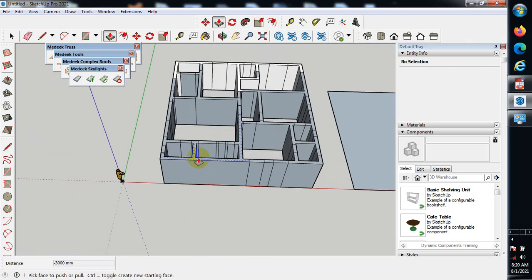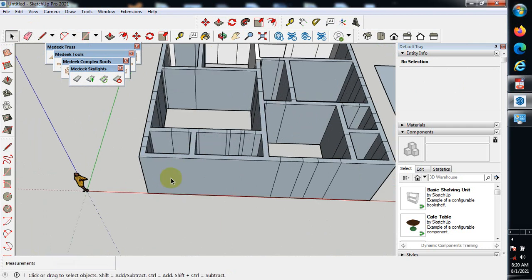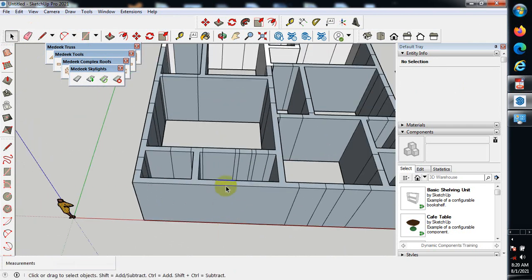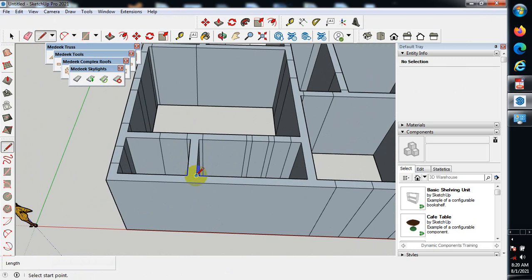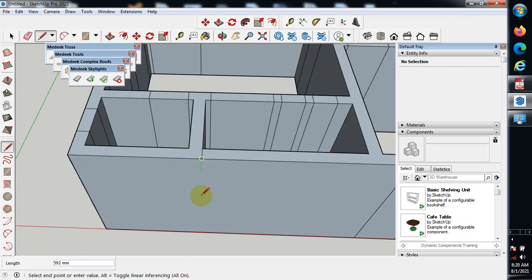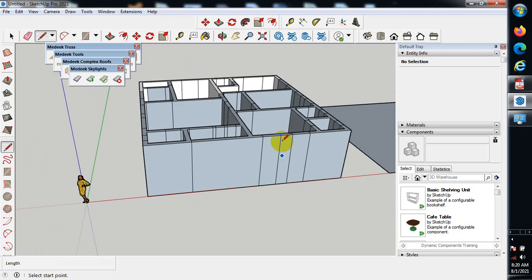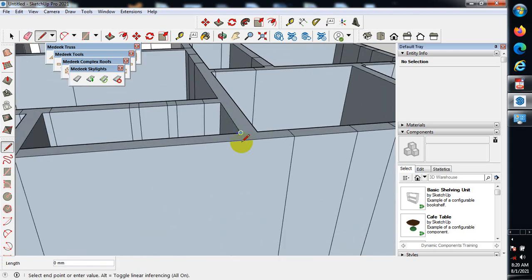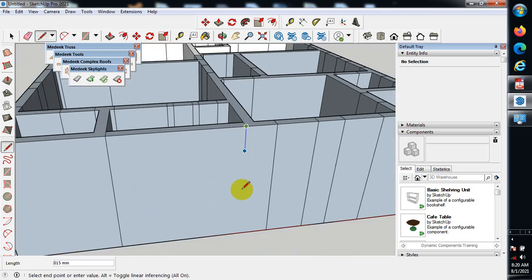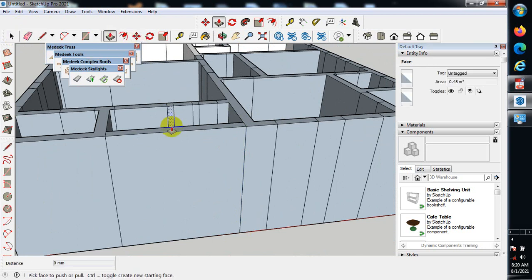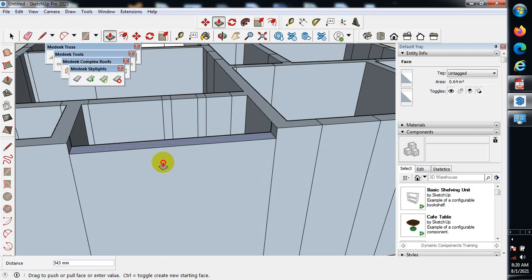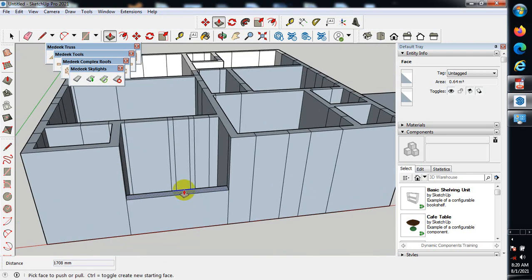All right, good. Now as you can see here, if you remember, we said this is definitely going to be our veranda, so I'll use a line here. I'll trace this down here. This is straight. Good. So I'll use press pull, push here. I can still use this to take this down.